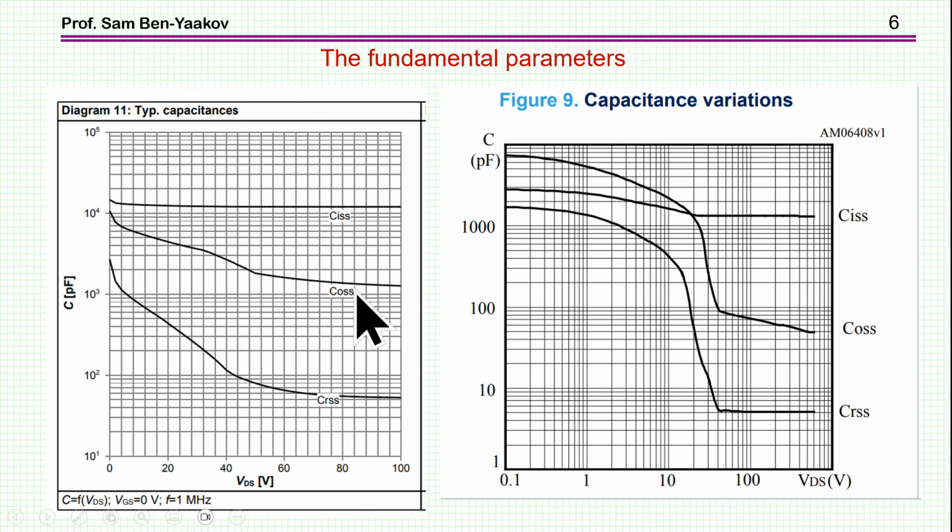But these are small signal capacitances, okay? They are not total capacitances, not large signal capacitances, or total, that is all the charge over the voltage, but it is a local capacitance for any given drain to source voltage, okay? This by itself is not very useful. You have to do something with it to get useful information.